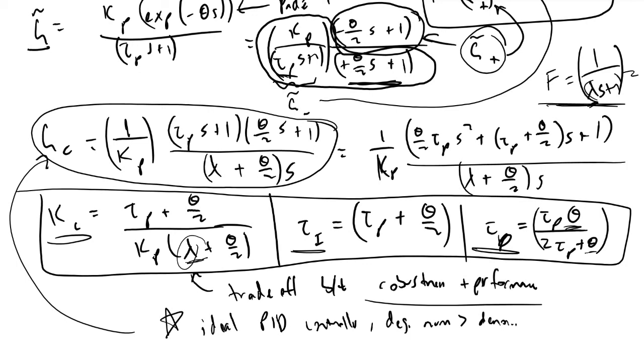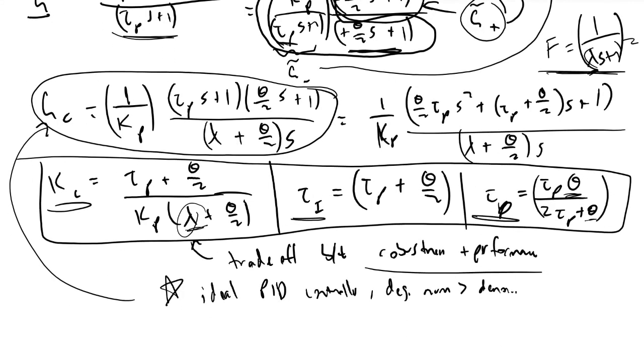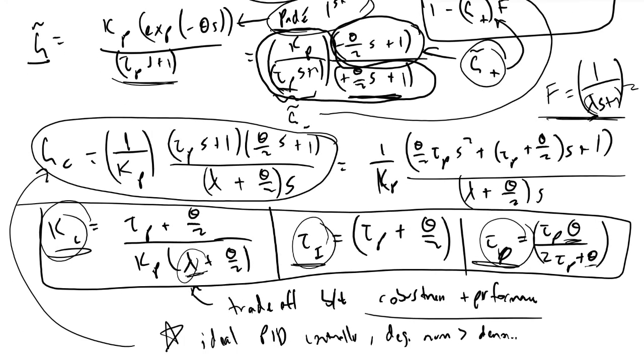And so the approximation also that we made at this point when we went with a first order approximation is something that in the textbooks they're only doing for first order processes. And so if we're working with integrator processes or gain processes, instead of Padé approximations, they'll turn to Taylor series approximations, just a first order Taylor series approximation, and it's all so that we end up finding what our PID tuning parameters should be. And a final note is that these functions are things that we look up in tables.